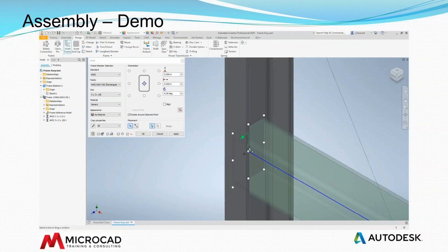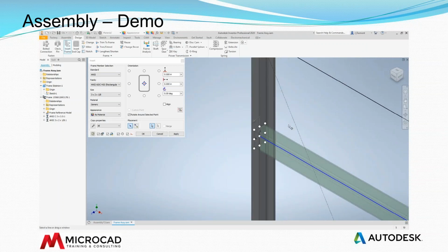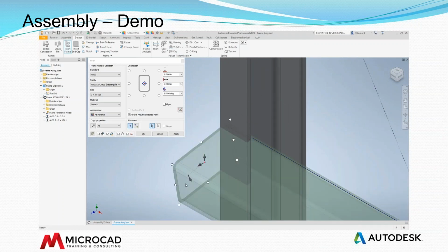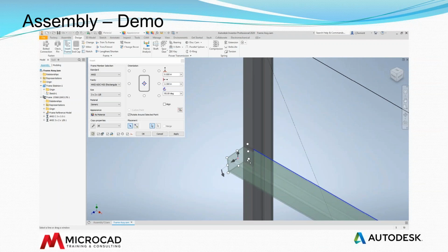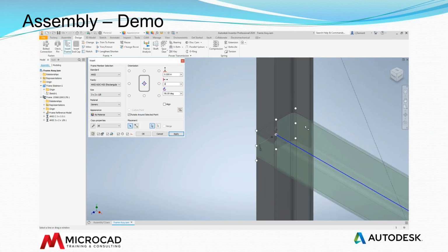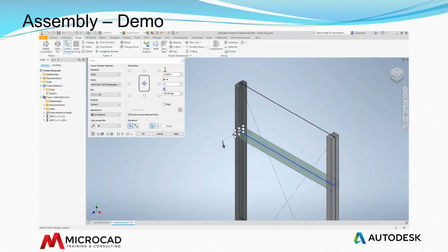This looks good. And then I have my control vertices, and this is what is called the enhancement editing tool. In the past, we'd have to pick an orientation and hope it was accurate. Now, all we simply do is click on these little directional arrows, vectors, and we can change its orientation. This is what Autodesk is calling enhancement. So you get the orientation about where you want it, and then you'll see the offsets update dynamically. So I'm going to locate it to the center of the member. I'm going to have all my offsets set to 0, and I've got my orientation set to 90 degrees, which is perfect. This is the orientation that I like.